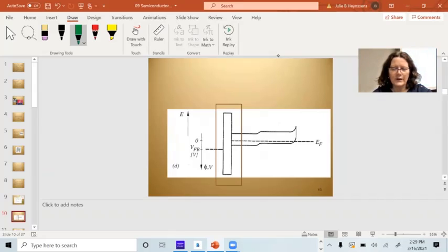Okay, so this is what I want to do. The big barrier right here is the oxide. And I can control what's going on the other side by the capacitive coupling. If this is an NMOS, I'm going to get positive charge here. The negative charge here can bend these bands. If I get enough negative charge here, I can bend these bands and cause it to look more flat across there.